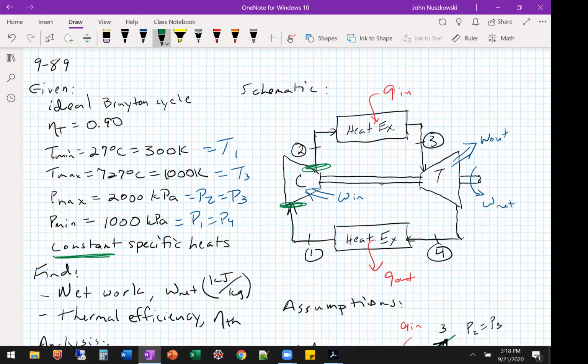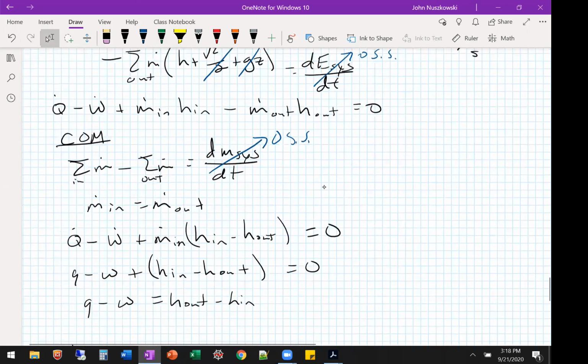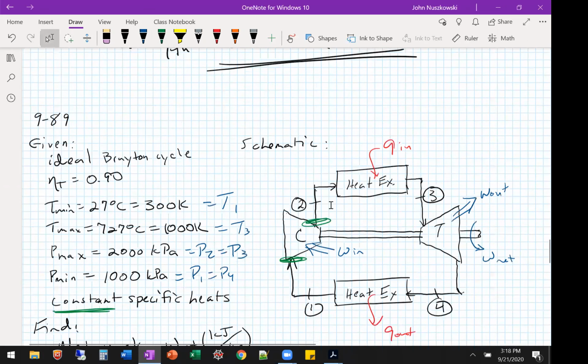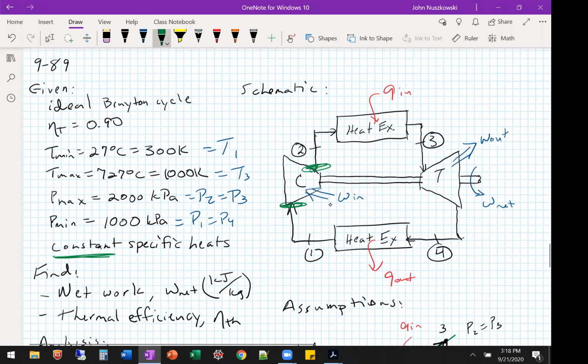The mass flow rates are equal, so we can use the conservation of mass that says the mass flow rates are equal, and then use rho VA to relate the mass flow rate at the inlet to the outlet. But it's not the same mass that's at this location that's at this location at any time. So the ideal gas law where you set the mass equal does not work that way. Okay, in the closed system, we have the same mass being operated as the piston moves up and down, but it's different as it works its way through the compressor.